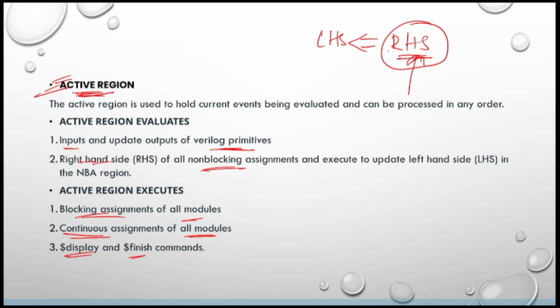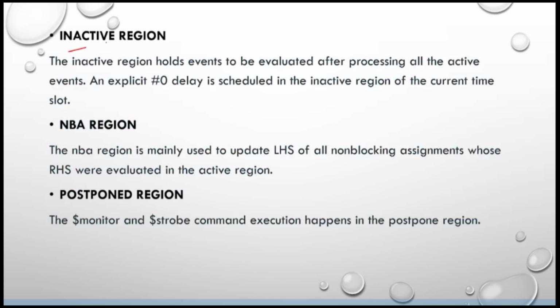So when it comes to evaluation, all the gate primitives and all the RHS of non-blocking assignments will be done in the active region. Similarly, when it comes to execution, when you are using a blocking statement, then the execution of RHS and assignment of LHS is also done in the active region. And also, system tasks like $finish and $display will be executed in this particular active region. Clear?